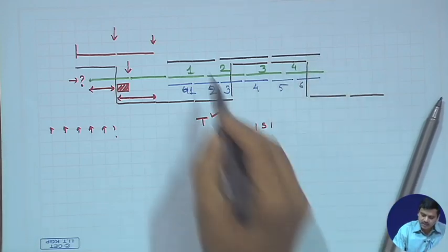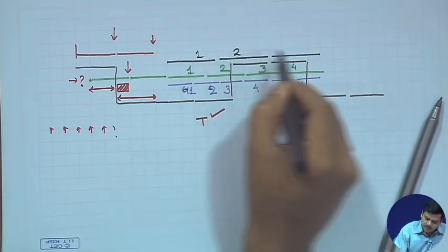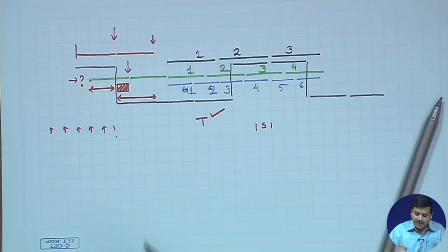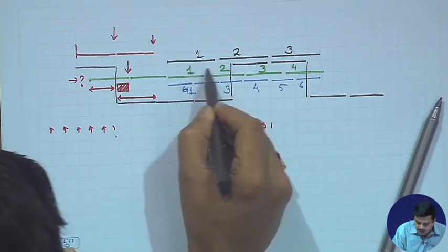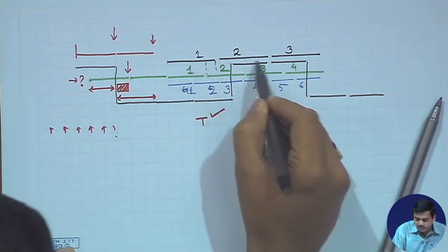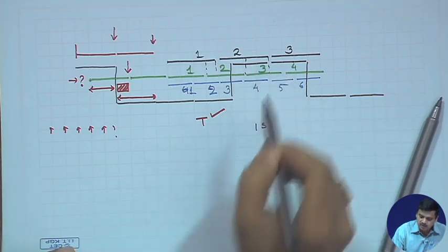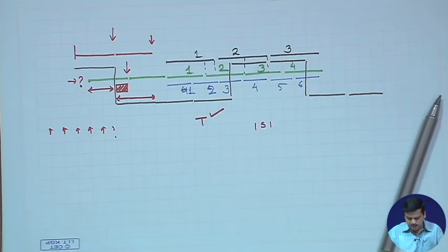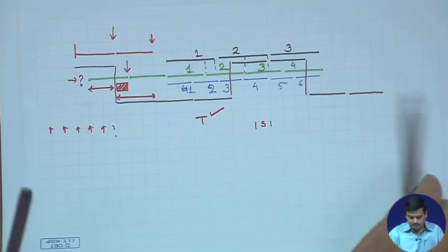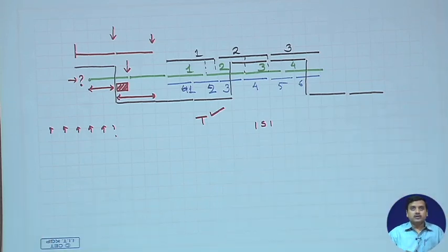So, that means in that same period the receiver has recovered only 3 symbols, and in this case there is inter symbol interference. You can clearly see there is inter symbol interference, right. So, the performance is terrible. So, at least through this we can definitely understand that we need to recover the clock at the receiver, or we need to find the clock which has an appropriate phase, otherwise things are not going to be as good as we have described in the earlier part of our course.